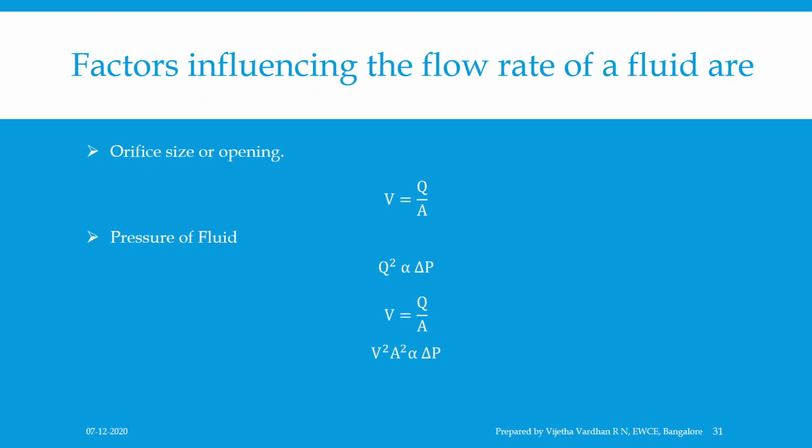Hence, it is not possible to maintain constant speed of an actuator using a conventional flow valve. Such valves are called non-compensated flow valves. And another parameter is fluid temperature. The viscosity of liquid varies with temperature and is inversely proportional to the temperature.